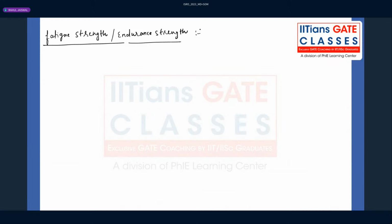Now, what is the definition of endurance strength? The definition says the maximum value of the stress amplitude, or the maximum value of the variable stress, which a standard polished specimen can withstand for a minimum life of 1 million revolutions under completely reversed bending load, right? Wohler was a scientist who performed the experiment by taking the case of completely reversed bending. He was applying a load that continuously varies from tensile to compressive.